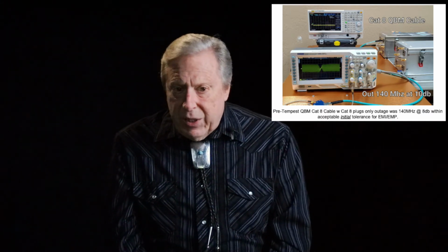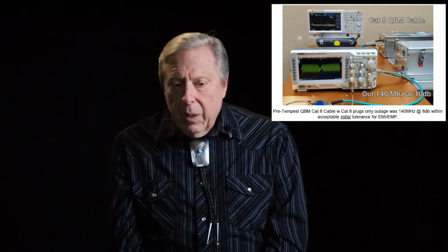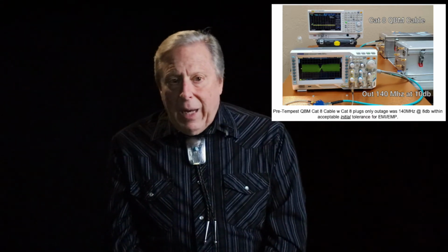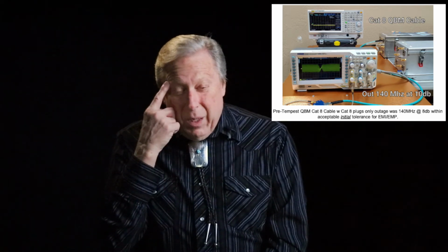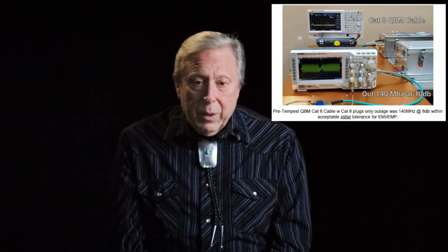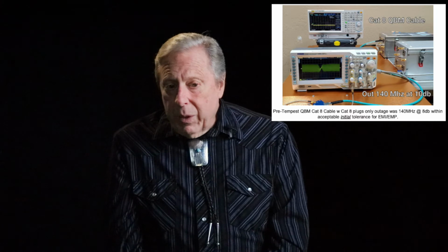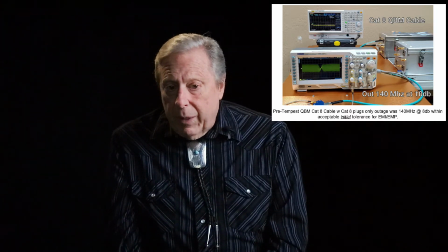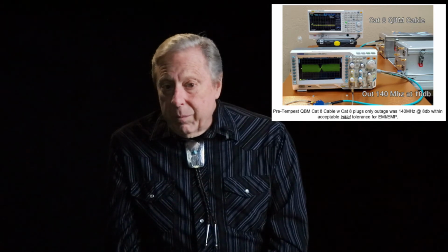What was nice to see was using the CAT8 plugs and jacks, even with a slight outage at 140 megahertz at 10 dB, which is really kind of small. Under most conditions for commercial, you wouldn't care. We didn't have an outage. And so initially, the tolerance level for EMI and EMP is really met.